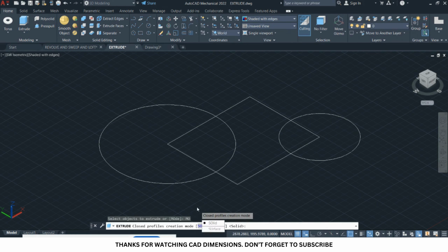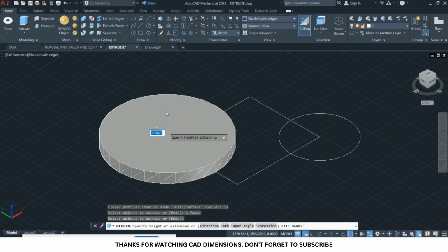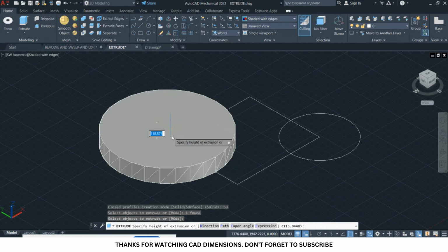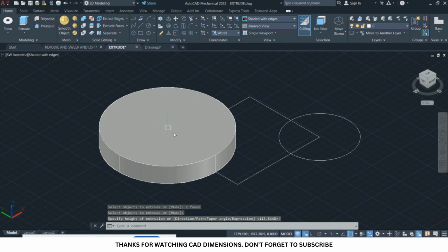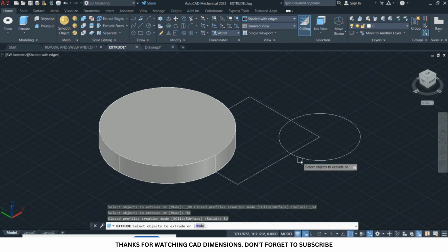That is, you can specify the mode of your extrusion, whether it is solid or surface. So if I select solid, for example, and I select this particular circle and I press enter, this extrusion is a solid extrusion. Okay, so that is it. You can specify the height of the extrusion, then you get it. Let's try another one. This time I want to use this circle. So I'll change the mode and I'll select surface and let's see what happens.